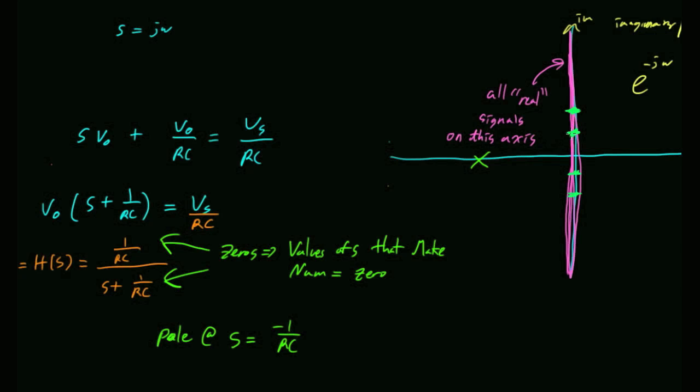But that's just assuming that you have a straight real value for the pole. What if you had a complex pole? Oh, if I had a pair of poles like this, yeah, we'll do that too. But it's the same concept. Even if I had complex conjugate poles, I still can't touch them. I still can't stimulate the circuit at that frequency.